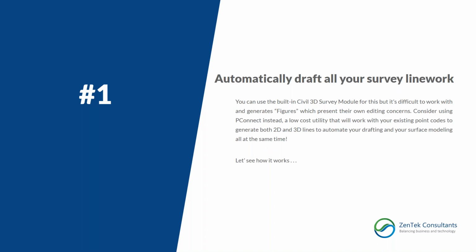The problem that I have with that is that it generates strictly figures, and survey figures have their own particular editing concerns. They're hard to use in terms of regular drafting and surface creation, and they have their own specific interface for making modifications, rather than the basic polyline and 3D polyline drafting that everyone's used to and has been using for decades.